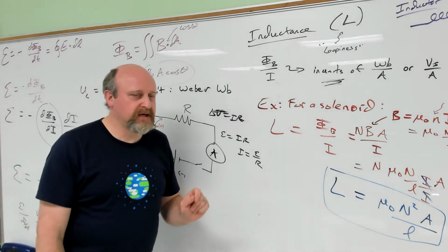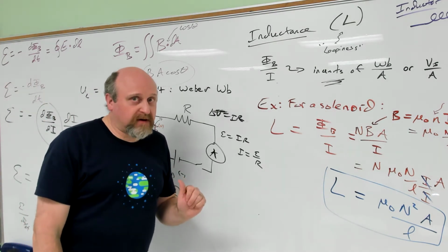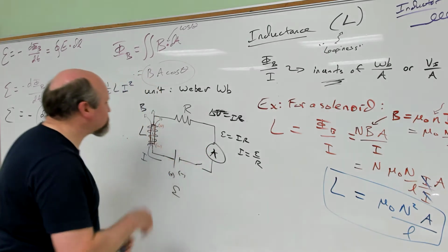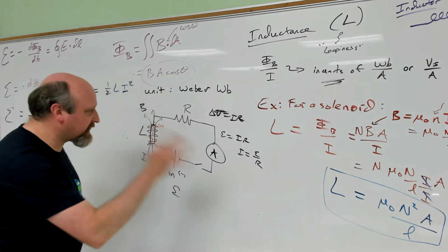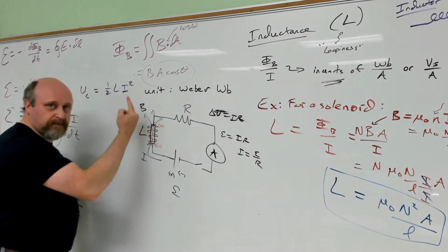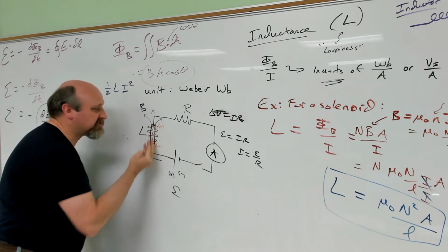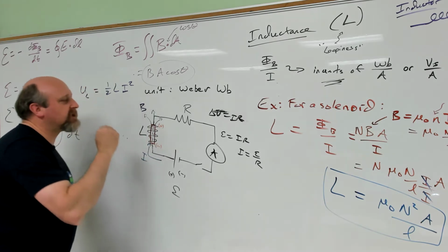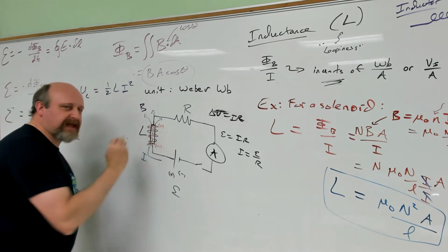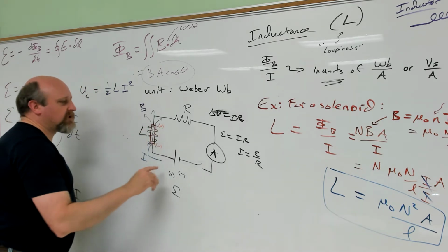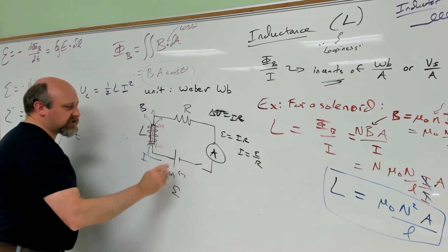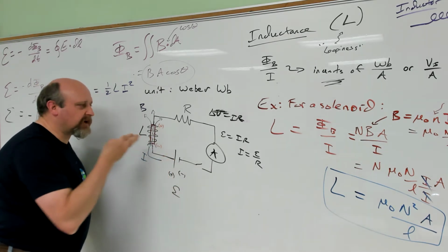All right. Good enough. So, wrapping up the main concept, if I have a circuit that's really loopy, that's going to make a strong magnetic field when I run current through, lots of flux, lots of field lines, then it takes energy to make that magnetic field. And so when I turn on, some of that energy is going to start going towards building up that field.